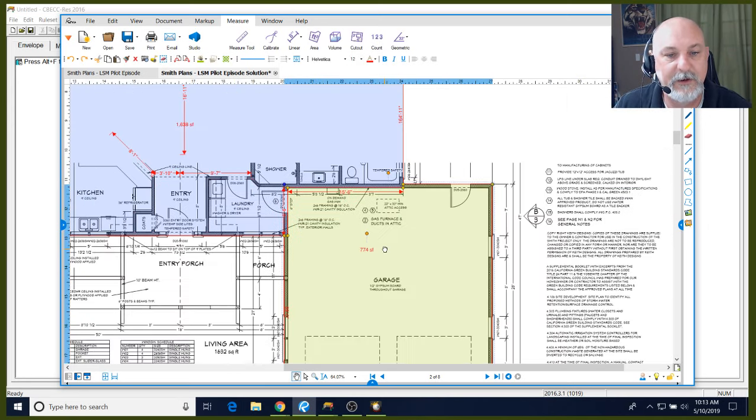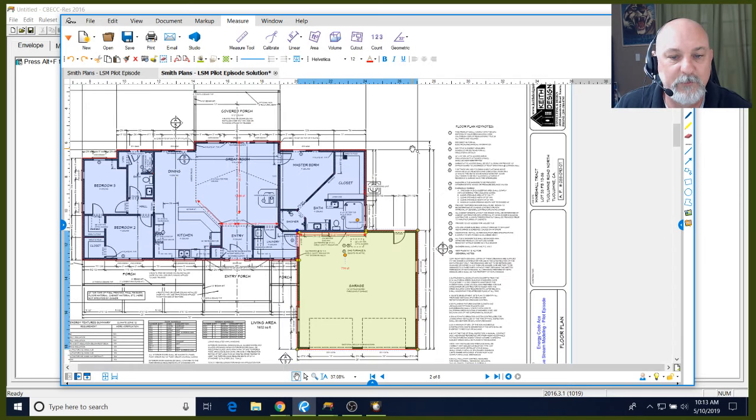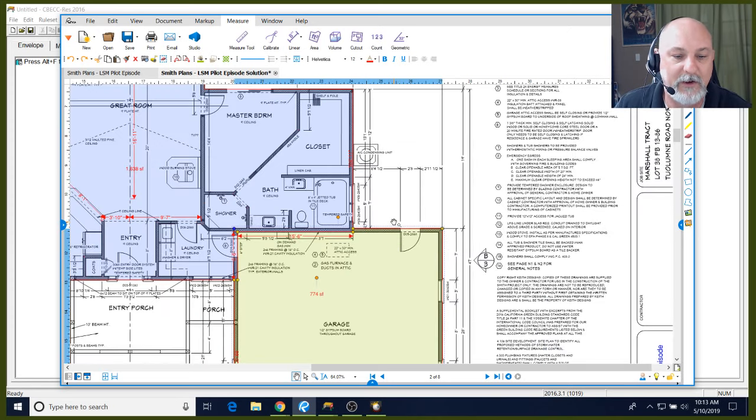Let's go ahead and grab our back wall. This is a little 12-foot projection. You see how I'm breaking out the wall area specific to the zone that I'm in. Right now I'm in the unconditioned garage zone, and I only have 12 feet of rear wall in the garage zone. So if I have 12 times 9.5, that gives me 114 square feet.